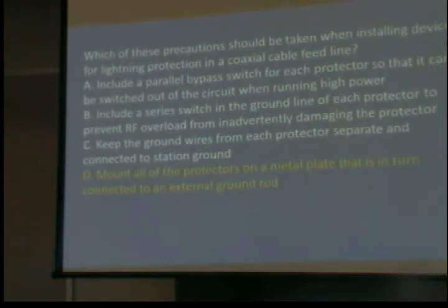Okay. If you're going to ground equipment, but not outside antennas, the third pin in the plug is a good ground. I've actually taken an extension cord, or a 3-pin plug, connected a wire to the big pin, and used that as a ground.